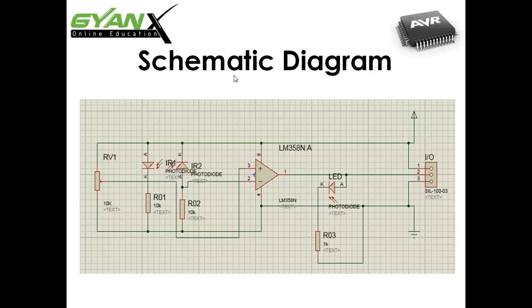Now let's see the schematic diagram of a digital IR sensor. This is a Proteus layout of a digital IR sensor, in which you can see we have connected the LM358, and here is an IR LED, here is a photodiode, which are connected through a resistor of 10k each, and here is our normal LED for sensing the output. And here is our potentiometer through which we can adjust our sensor as per the environment condition. So in this way you can make a schematic diagram and design your own digital sensor.